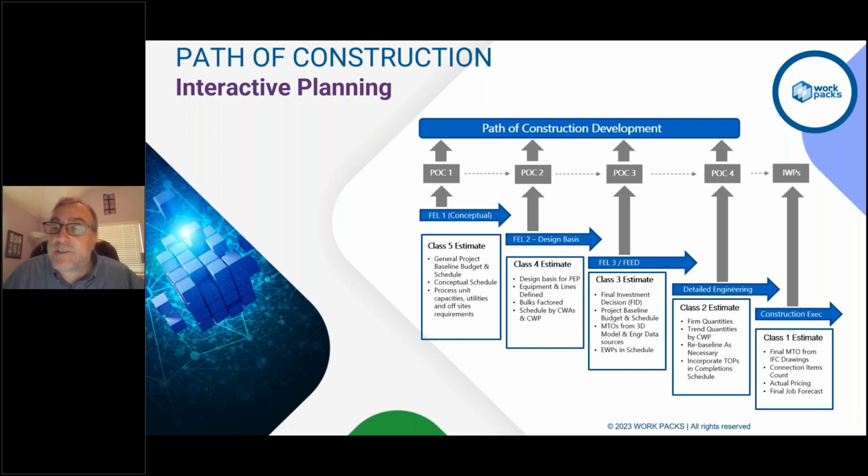Then you're at a production control level with the installation work packages, and setting up a constraint management process in a production environment, going out to the field, making ready all those work packages with the goal of having a 3 to 6 week look-ahead of constraint-free work packages before they're released out to the field. If you don't have that, you can almost predict that you're going to have schedule and cost overruns. But this is how we avoid a lot of those 33% schedule and 25% cost overruns: by getting more disciplined around the path of construction in these planning events.